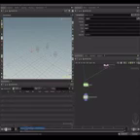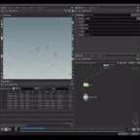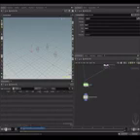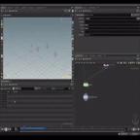But what we are interested in is the other object ID. And this will tell us whether this RBD packed object is impacting the static object or the ground plane. So as you can see here, the other object ID is 1, which means it's the static object, and here you have ground plane collisions.